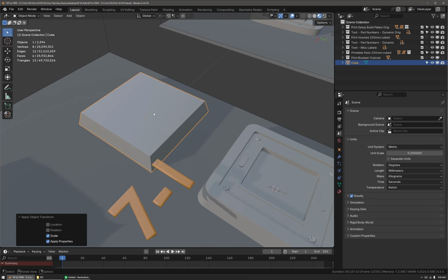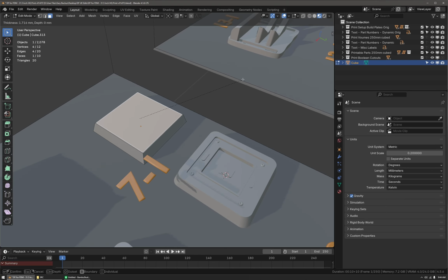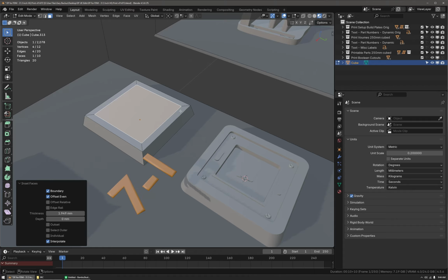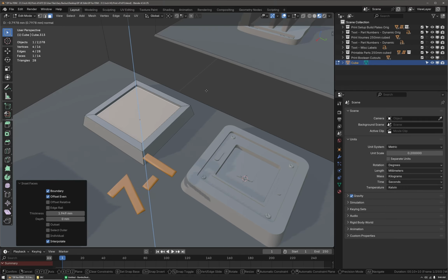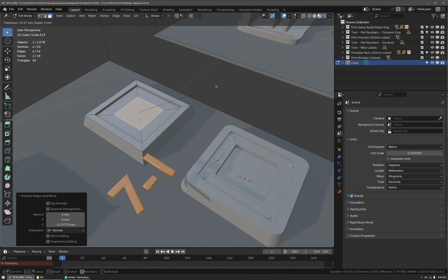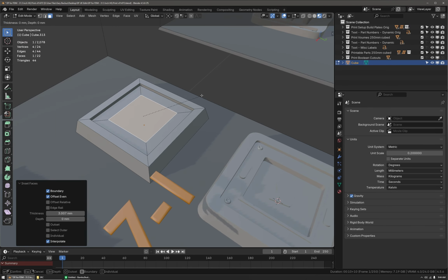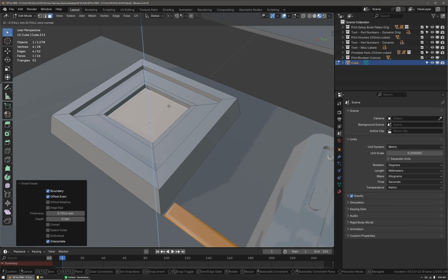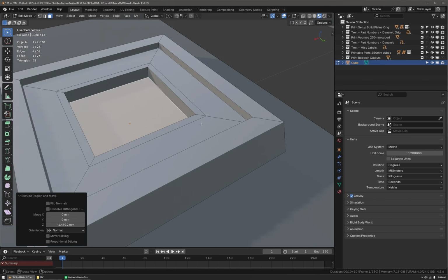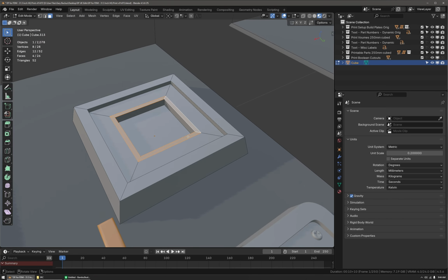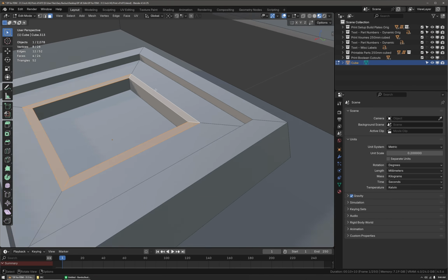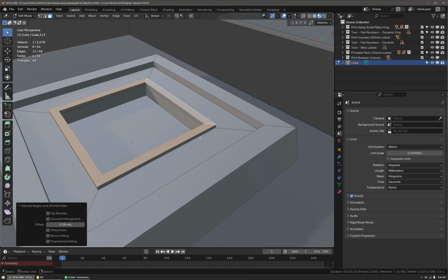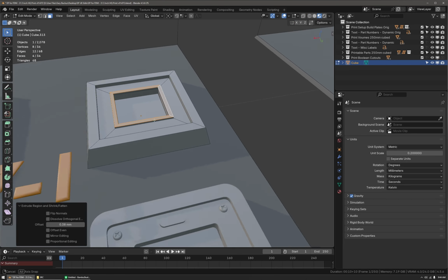expected. So I'm just going to select the top face and inset, and then extrude with E, and then inset again with I, and then another inset, and then another extrusion. So you have to be mindful of topology when you're doing polygon modeling. So you have to set up the geometric detail to facilitate new details. So I'll press Alt-E, extrude faces along normals from that face loop selection there.